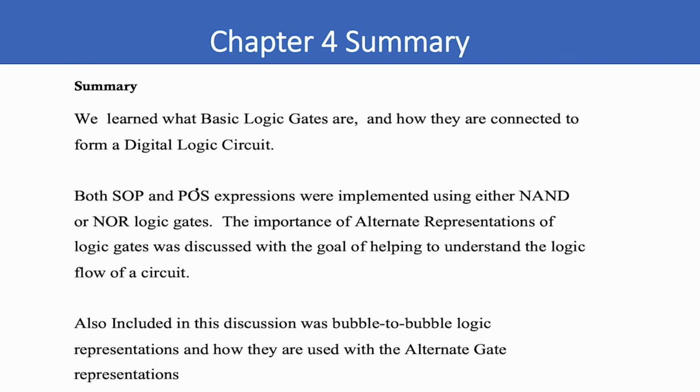Well, this is the last video in basic gates, and what we learned was the basic gates that are used to implement digital logic circuits, and it's basically the inverter, AND, and OR functions. And those AND and OR functions can be implemented using either NAND gates or NOR gates. And the NAND gate or the NOR gate can be used to represent inversion. We implemented both sum of products and product of sums expressions using either NAND or NOR logic gates.